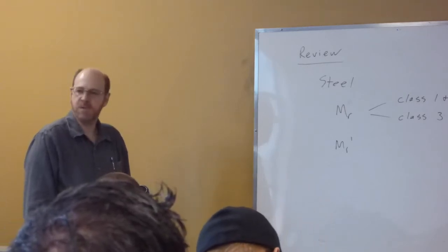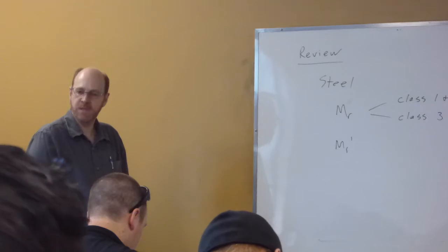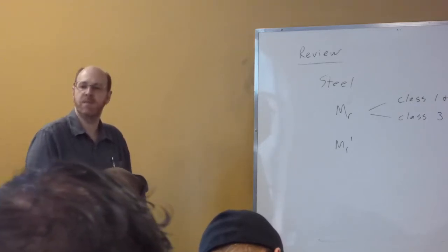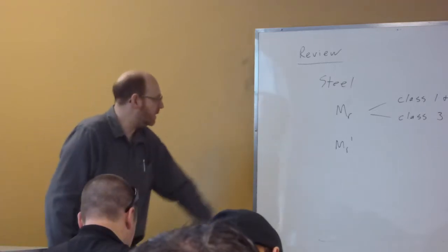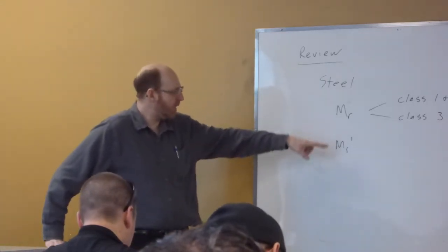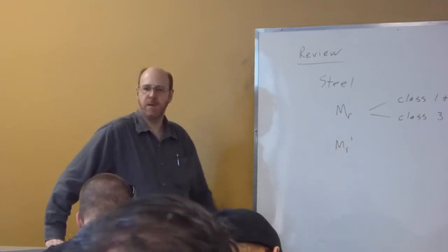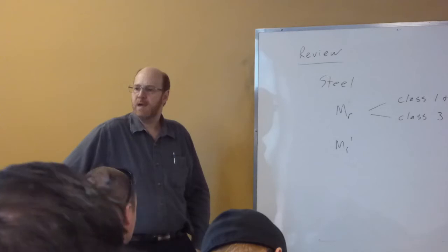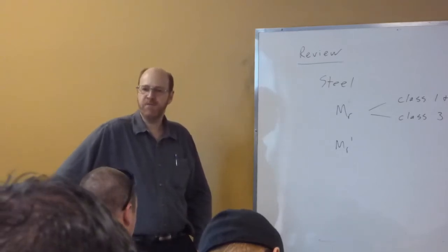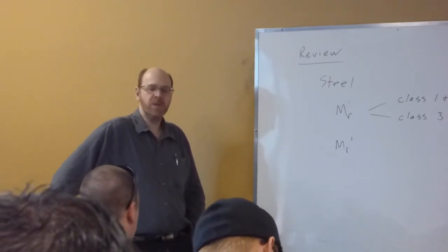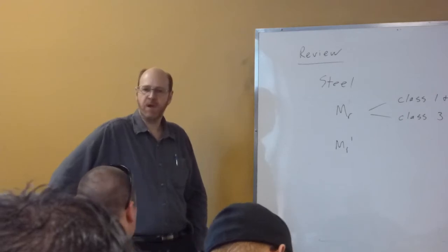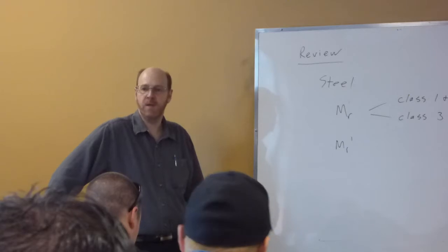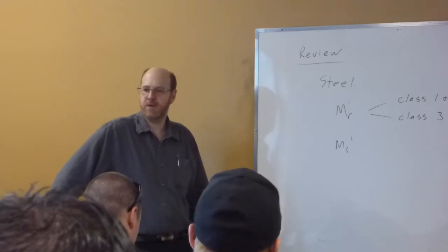The typical examples that we looked at are things like a Gerber girder system, where I've got negative moment at the supports and positive moments in the main span. So for my positive moment, I'm just going to be calculating MR, but for my negative moment, I'm going to be looking at this MR prime. Now, even with MR, if I've got what appears to be full lateral support, I need to look at what the spacing of that support is. If I've got joists that sit on top of beams and the joist spacing is 3 meters apart, there could be a slight reduction factor.